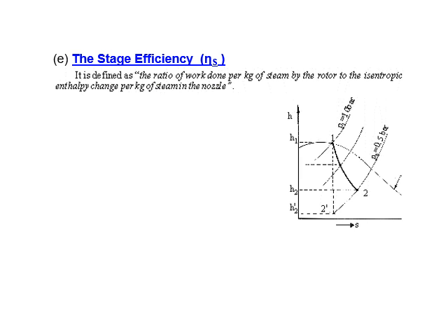The line 1 to 2 represents the actual enthalpy drop in the turbine. Position 1 represents the enthalpy at the inlet of the steam to the turbine. At that time the pressure may be maintained at 10 bar or more than 10 bar. Then the steam flows through the rotating element or the rotor, its enthalpy drop occurs, and finally the steam exits at the lower pressure.